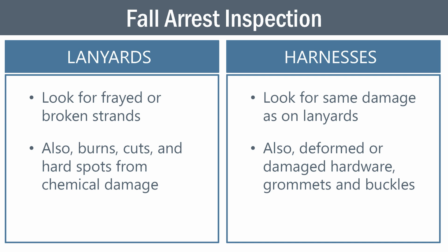Now, another question people should ask is, what if it goes through a fall? What do I do? If you're in a fall arrest system and it goes through a fall, you take it out of service immediately. Okay? You don't use it again until it's been recertified by the manufacturer. Now, some people say, Ronnie, that costs a lot of money. I understand that. Sometimes it's cheaper to buy a new one. Okay? But think about it.